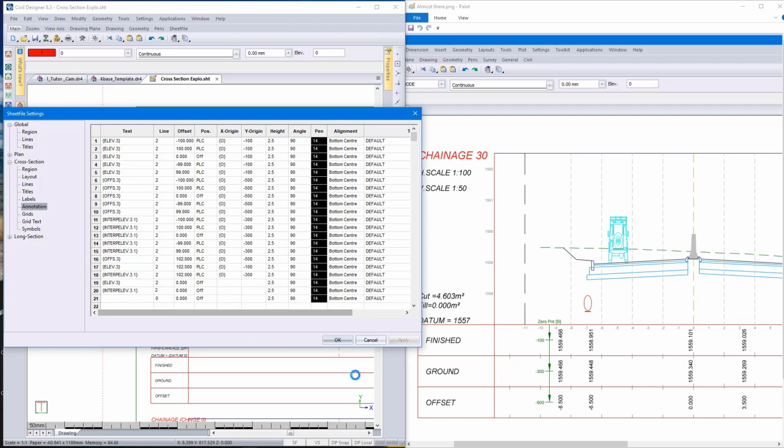And then the last one, if you look over here, is the offset. I'm going to right click there and select offset. All of these with 0.3 means that you're asking for 3 decimal places. That too is the offset on your final design. Moving on to offset and position. If you're going to leave this as off, you're referring to offset. So if, for instance, I put in -2 as an example, that would be 2 meters to the left of the center line.